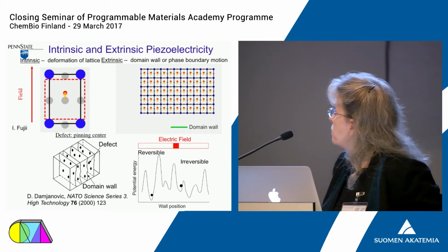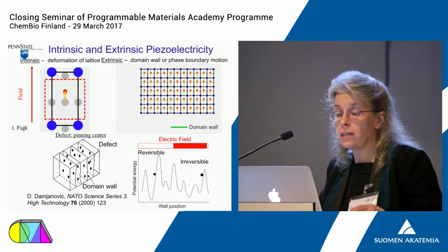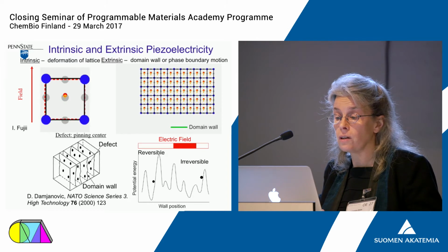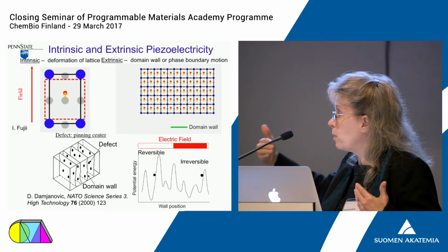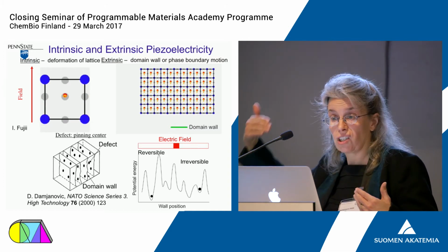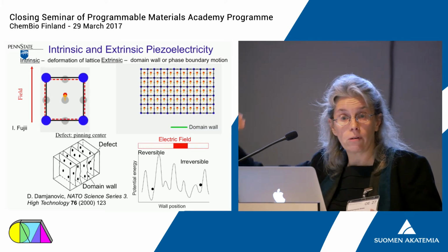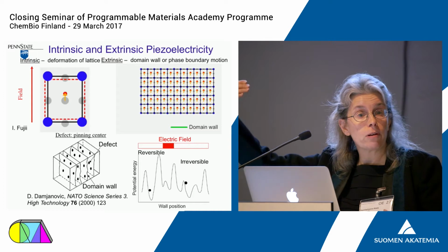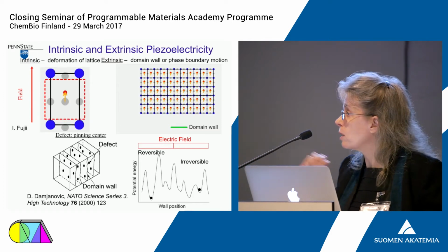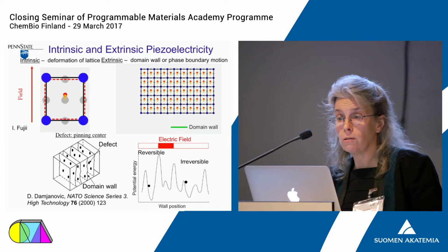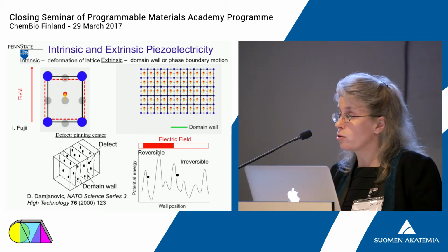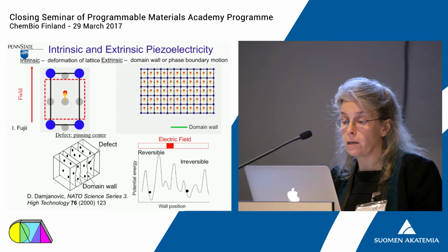And the net result is that if I look at the potential energy as a function of position in the solid, I will end up moving domain walls from a deep potential well where I can excite it from the bottom of the well with an electric field, but when I pull the electric field off, it will tend to recover to its original position, so that I will have a reversible contribution to the piezoelectric response associated with the motion of the domain walls.